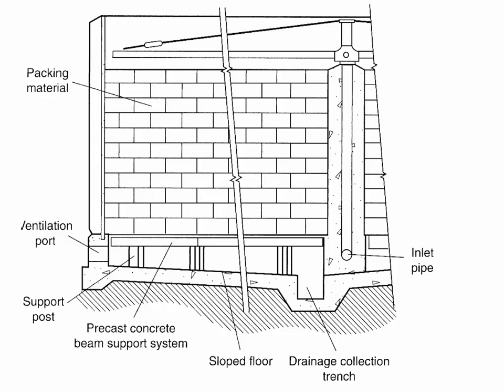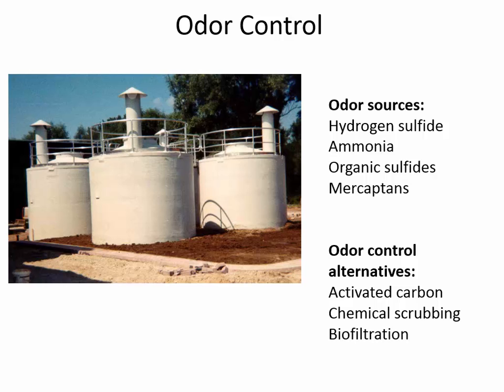If it's a rock filter media that's being used, then it may be necessary to have a pretty rugged and robust reinforced concrete support structure underneath the trickling filter. But the structural requirements are a lot less intense if plastic media is used in place of it.